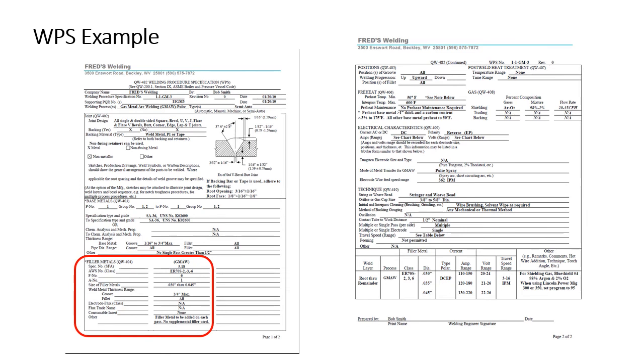And when you're reading these, sometimes it takes you a while to figure it out, but on a WPS, you need to list all the essential variables as well as non-essential variables. But key, we're talking about essential variables. All essential variables need to be addressed on the WPS. You don't have to use this formatting example. This is a code suggestion, but if you want to come up with your own and your guys can read it and your client's happy with it, run with that.